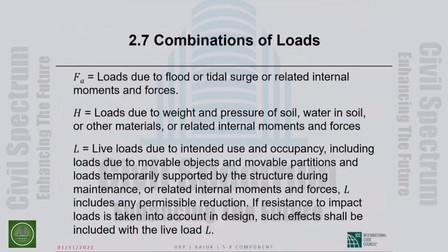F sub A, flood loads, very difficult term to come up with, as I'll discuss a little bit later on. H, loads due to weight and pressure of soil, water in soil, or other materials, or related internal moments and forces. So typically I call it horizontal earth pressure. That's what it is. And that includes the weight of the water that is in the soil.